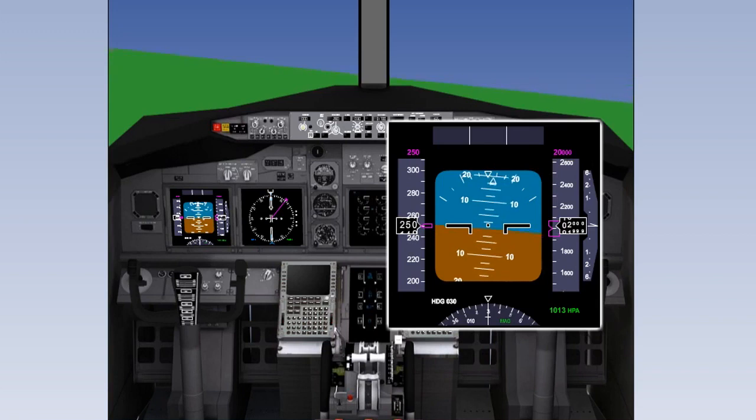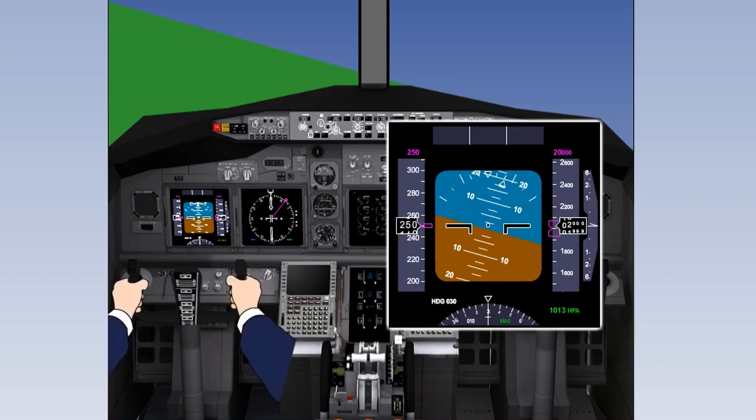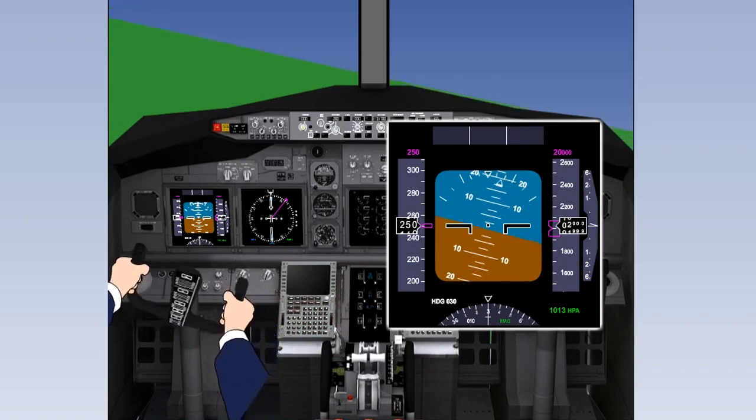In the event that a gust displaces the right wing upwards, the change in attitude will be noticed by you. By looking at your reference value, you will be able to mentally assess the rate and magnitude of the displacement. That will then allow you to mentally calculate the correction required to bring the aircraft back to wings level, and apply that correction to the controls.